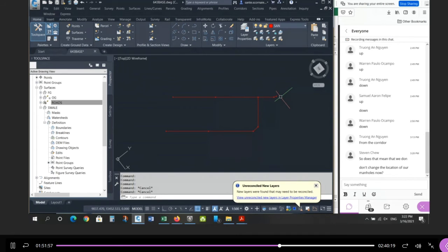The next thing will be a review of what we did in CDA for the most part. Stephen, one common mistake was to make this pipe go from here all the way to here. They made this one pipe. If you don't have a maintenance hole in between this one and this one, you should put one in. It's too far, right? If you measure the distance from the center here to the center here, you'll notice it's bigger than 150. So you need at least one maintenance hole here, and for the same reason, you're going to need one here.